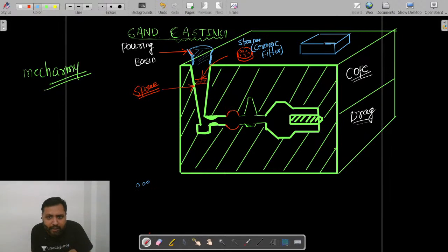Why? Because if you made these holes too small in size, do you know what will happen? When you pour the molten metal here, if these holes become too small, because you wanted to filter the too small impurities, then what will happen? Molten metal will not come down with a continuous flow. It will start coming down drop by drop, and that is how you cannot fill the cavity. Yes, so these holes are basically not too small. It is small but not too small, right?